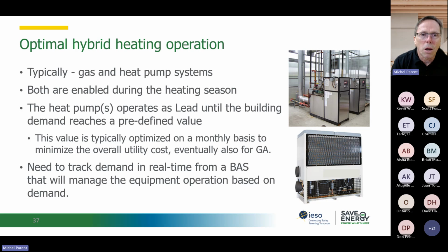You should not install a heat pump of any significant size that has supplemental heat without tracking your demand, because now you can manage that demand, usually on a monthly basis, because your peak demand is charged on a monthly basis. And I'm disregarding GA right now, but if GA was in play in the winter, you would also manage based on GA. And you will really turn off the heat pump when you see that your peak demand has reached a preset maximum. And usually that's based on an economic calculation. And I'll show you an example.